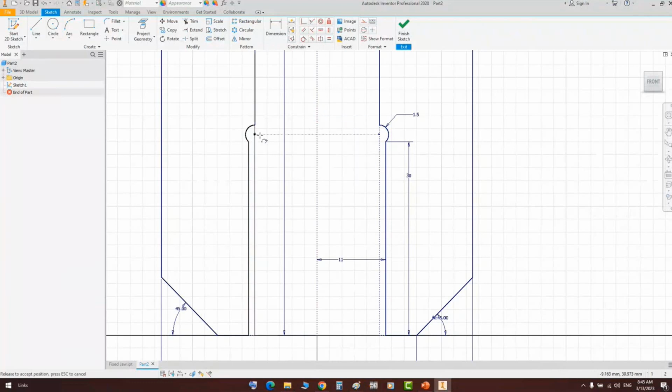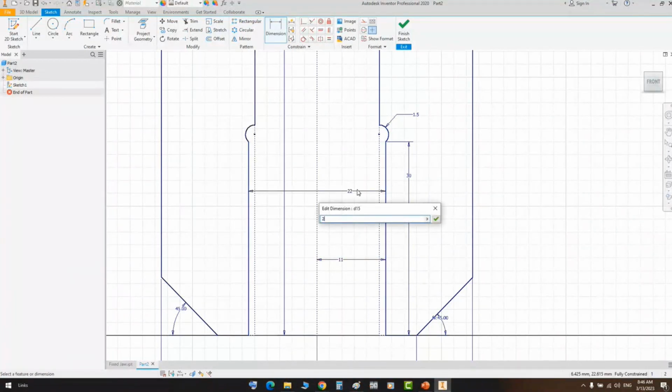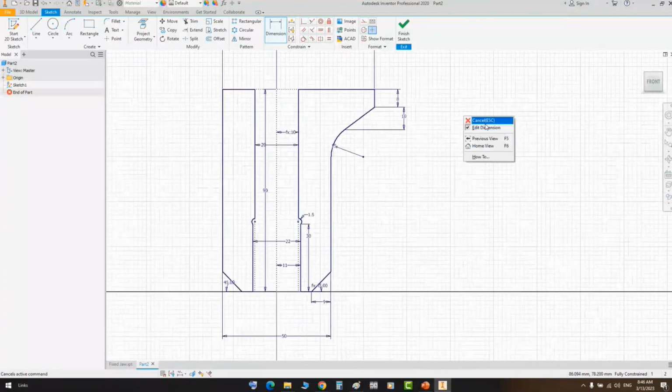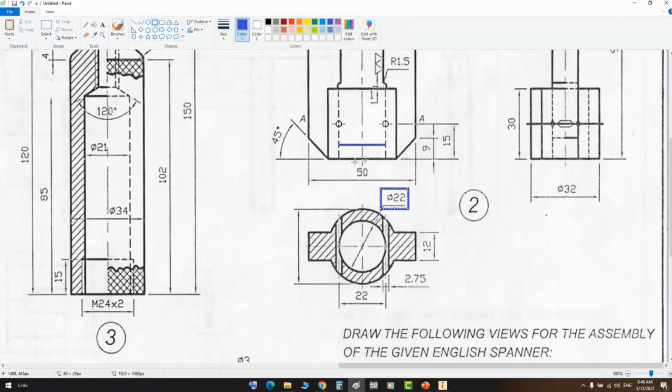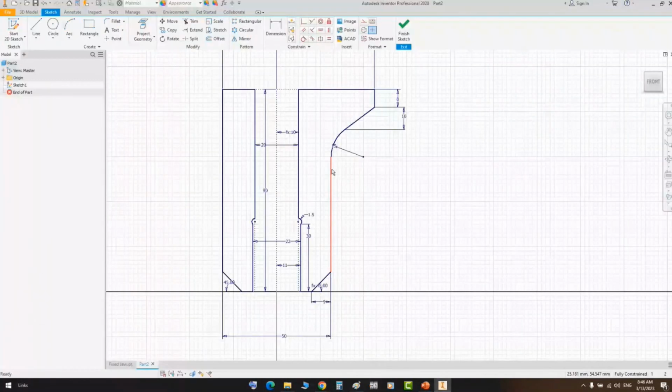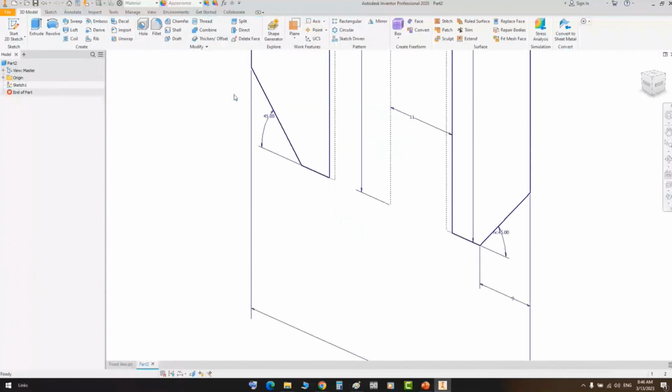Okay. Now you can figure that this line can be moved right and left, because we need to define the offset from here. So the offset from here to there is 22 millimeters. Now you can figure that the sketch is completely fixed. Now let's make an extrude for this sketch to create those parts here and that one. Okay, so come back here, and let's click finish.